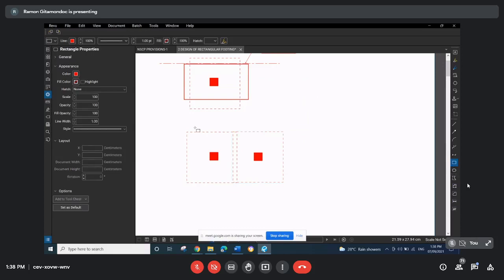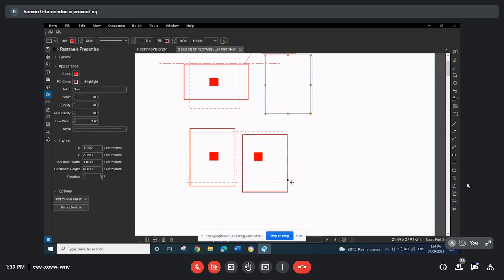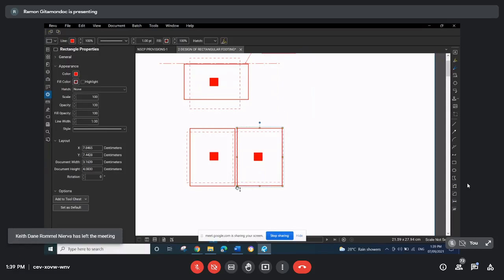So in order to avoid overlapping of the footing areas, instead of a square footing, we will use rectangular footings. So we maintain a small space between the two footings, no. So the footing will now be longer on this side while shorter on this side. So what you will have is a rectangular footing. Okay.